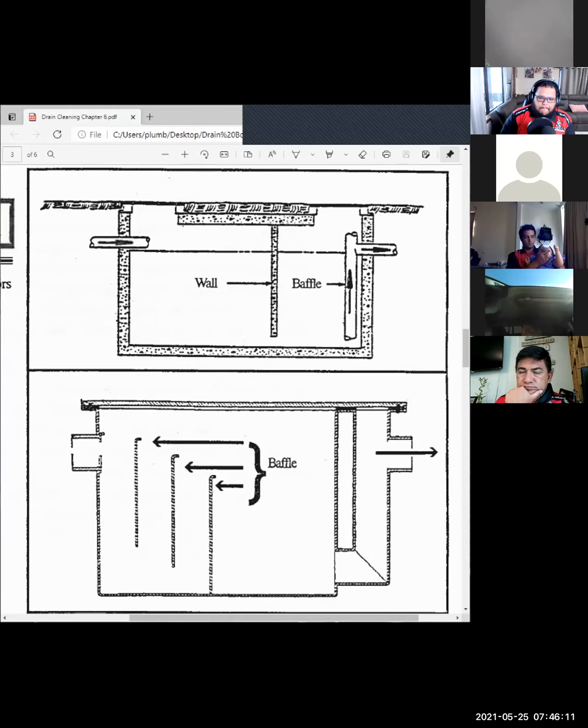So if you're going to pump every 3 months or quarterly, or every month, depending upon your loads, the grease trap guy is supposed to have the knowledge. He has a stick and he pops that mantle, and that's the depth of the mantle. The thickness of the mantle dictates the frequency of pumping.